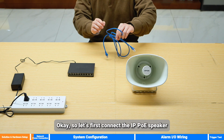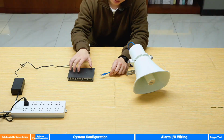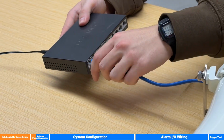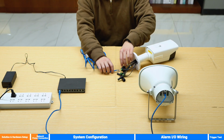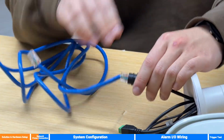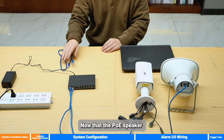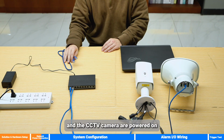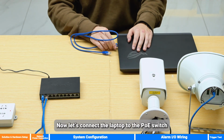First, let's connect the speaker, the CCTV camera, and the laptop to the same network switch. So first, let's connect the IP PoE speaker. Now to the CCTV camera. Now that the PoE speaker and the CCTV are powered on, let's connect the laptop to the PoE switch.